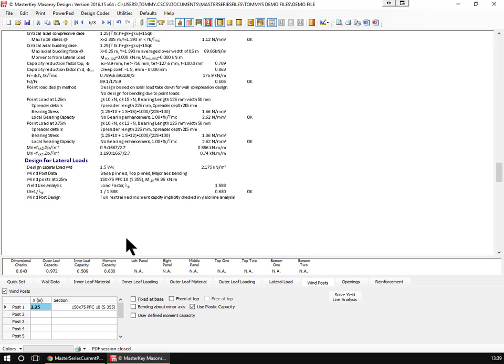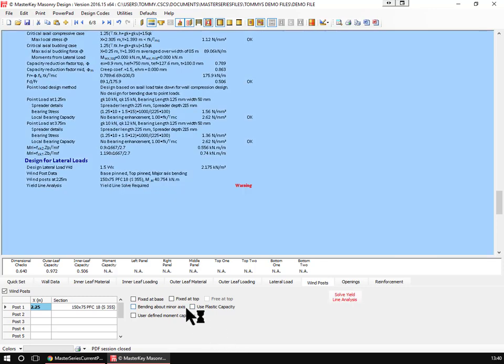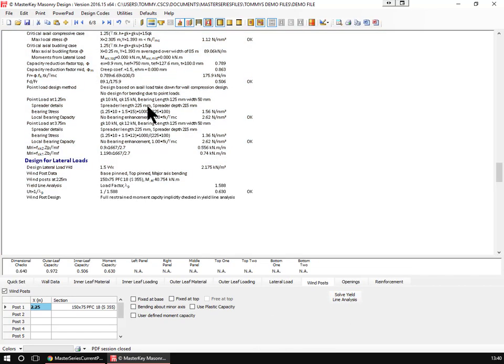So therefore it is working as an elastic component and giving the restraint it requires. So it is inherently designed, the post, in this design criteria. It's designed the post, with, in this case, a plastic capacity of 46 down to elastic capacity of 40, won't make any difference because it wasn't going to yield in that direction anyway, so it's giving us no difference in our overall unity values.